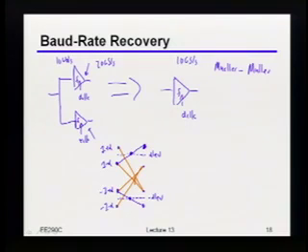So again, I just mentioned this because this is kind of an interesting approach, and in particular, you remember we talked about the DFE having weird timing interactions and messing up the edges? Well, if you really were to use one of these baud rate types of recovery loops, then potentially that avoids some of those issues. Because again, you're really looking at the real sample position and trying to align things based upon that. Does this make sense to people? Okay, great. So unless there's more questions on this, this is actually most of what I had to say in terms of, let's say, the CDR design itself.